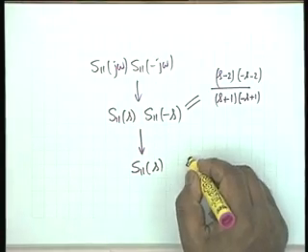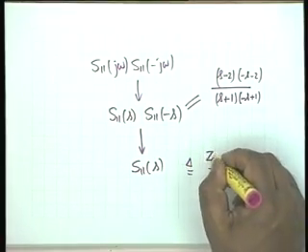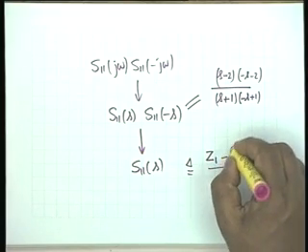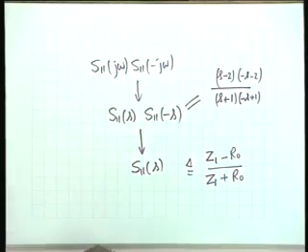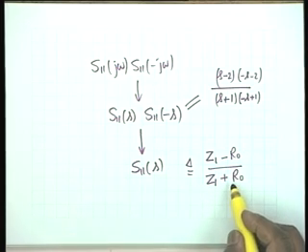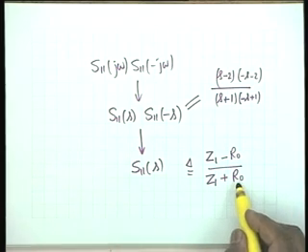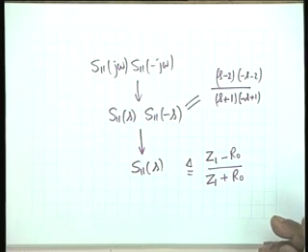As far as the denominator is concerned, the choice has to be unique. Why? Because we go back to the definition of the reflection coefficient. It is the input impedance minus R0 divided by input impedance plus R0. Okay. And the poles of S11 are the zeros of Z1 plus R0. Z1 plus R0 is an impedance function.